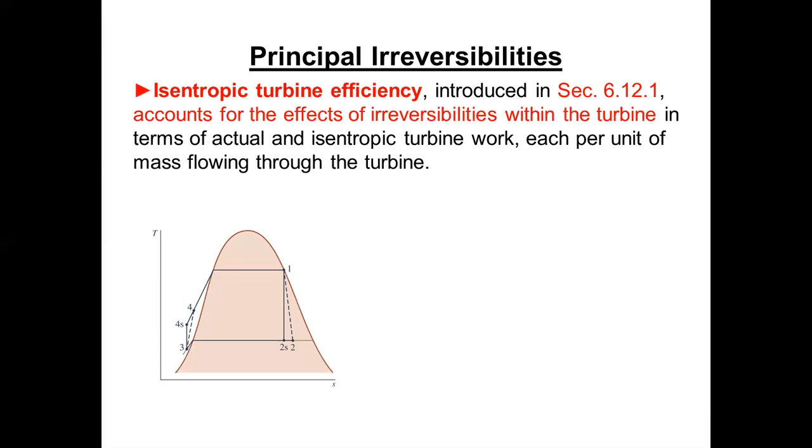You can do that, but if you do, you always get roughly the same number, about 98, 99, 99.5% thermal efficiency on a turbine. It's because they're very small losses. You've got a tremendous flow of energy through that turbine, a high steam flow rate. You have a little bit of heat loss, but they wrap them up with blankets. So the heat loss from the surface is insignificant. The BTUs per hour of heat transfer is minuscule compared to the amount of energy flowing through that turbine.